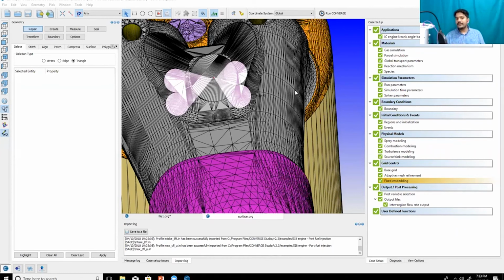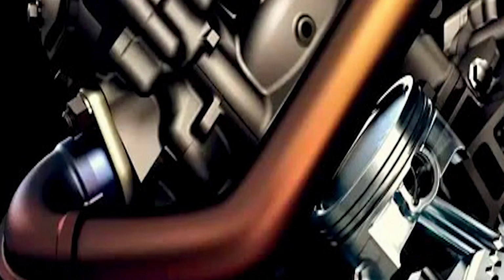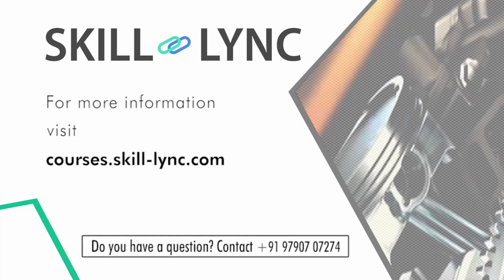Your turbulence model has that limitation, that is, it is valid only up to a particular grid size. If you make the grid much more refined than that, your wall quantities will be wrong. With respect to IC engines, it's not a big deal, but the way you will see that effect is it's going to increase, say, the wall heat transfer, which is going to cause a reduction in the peak pressure.